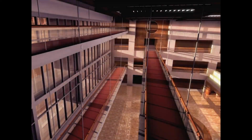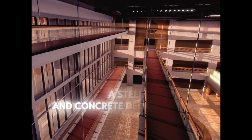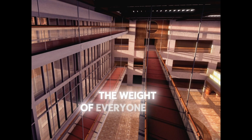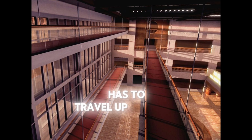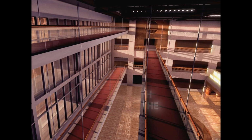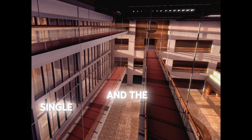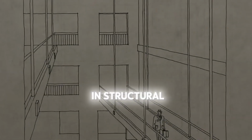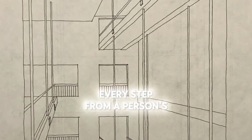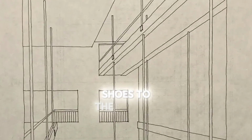Start with what a walkway like this actually is. It's a bridge indoors, a steel and concrete deck spanning the atrium with nothing under it. All of its weight, and the weight of everyone on it, has to travel up through hanger rods into the roof structure. That path is called the load path, and the single most important discipline in structural engineering is being able to trace it, every step from a person's shoes to the ground.